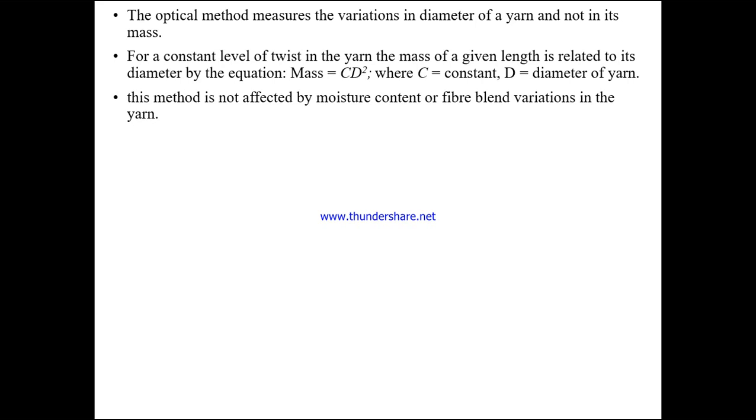If you are going to use different blend ratios, such as 80-20, or 60-40, or 70-30, in every case, though you are using the same yarn count with the same mass irregularity, you will still get a different value due to the differences in the dielectric constant. So this is also one kind of drawback, or limitation, of the Uster unevenness tester.